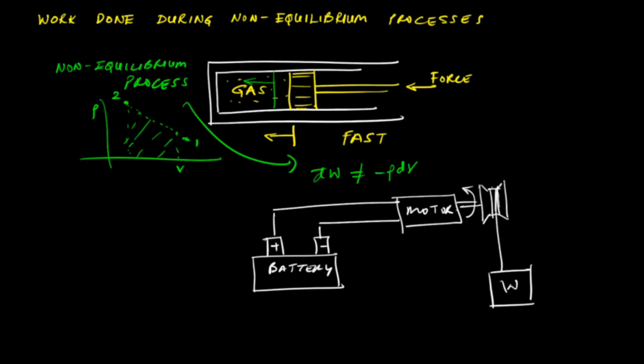Now let's look at this case. If we consider a system boundary such as that shown in this red dashed line, then our system comprises the battery and motor. In this case, clearly the system that is enclosed by the boundary does work. In fact, the work crosses the boundary where the system boundary intersects with this shaft. And this work can be associated with the torque acting through the angular displacement.